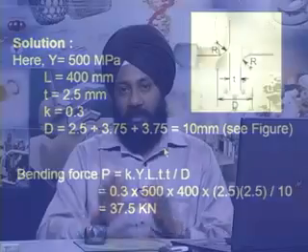So, we have seen till now that using a very simple mathematical formula, and depending upon the die that we are using to convert a sheet metal into a bent sheet metal, or when we create a bend in a sheet metal using a die operation, we can very easily calculate the bending force. The parameters required are the length of the material, the thickness, the type of die that we are going to use, as well as the yield stress of the material, given as 500 megapascal.